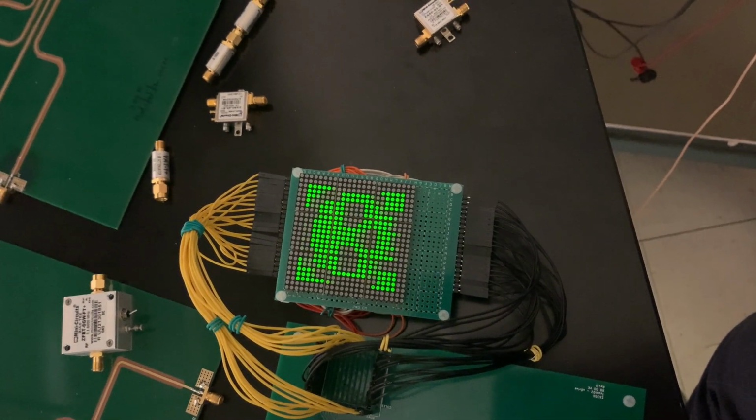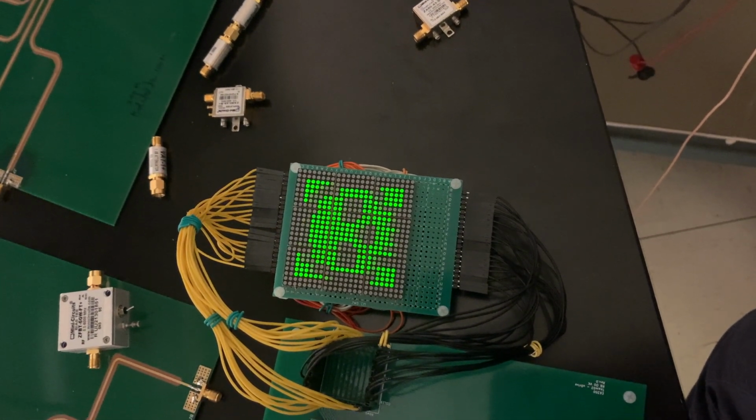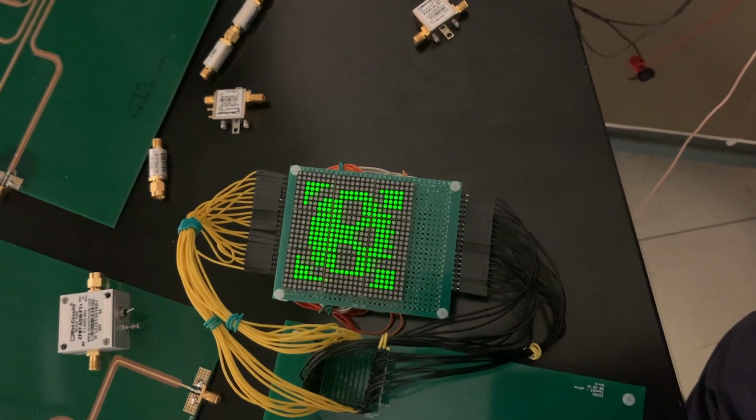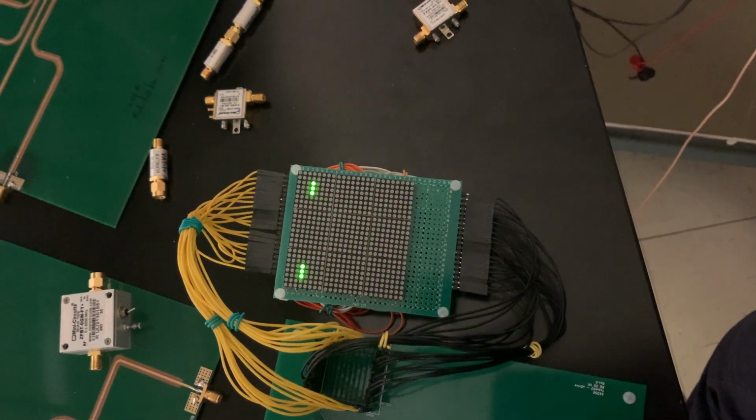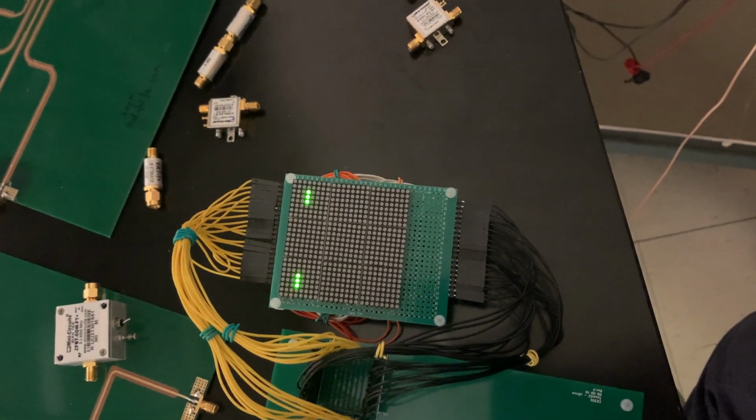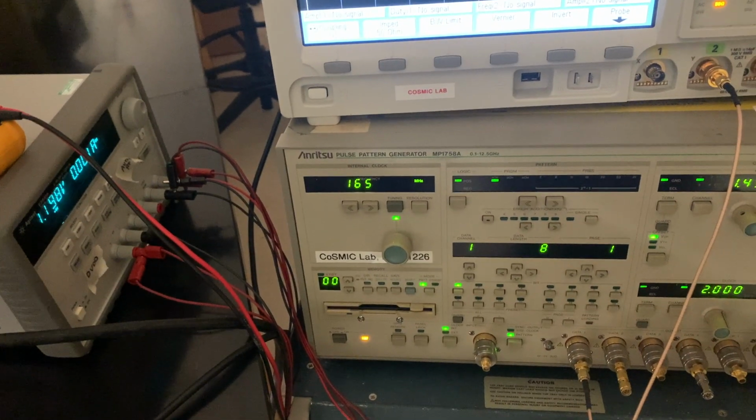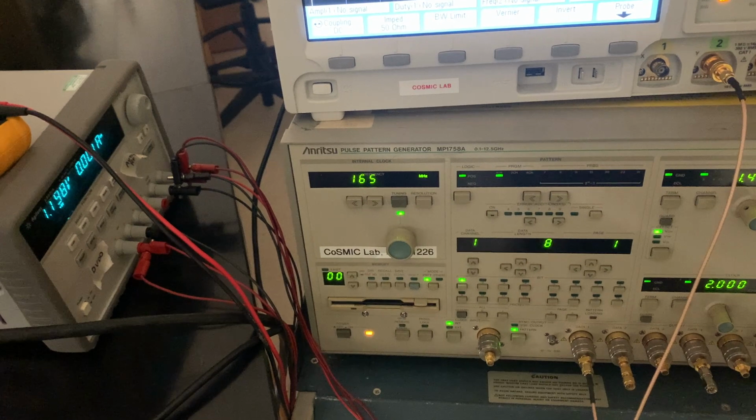In this video, the clock speed is constantly being increased in steps of 1 MHz, and we see that when the display fails, the clock frequency is 165 MHz. This indicates that the maximum clock speed in this setup is approximately 164 MHz, which corresponds to a refresh rate of 512 kHz on the display.